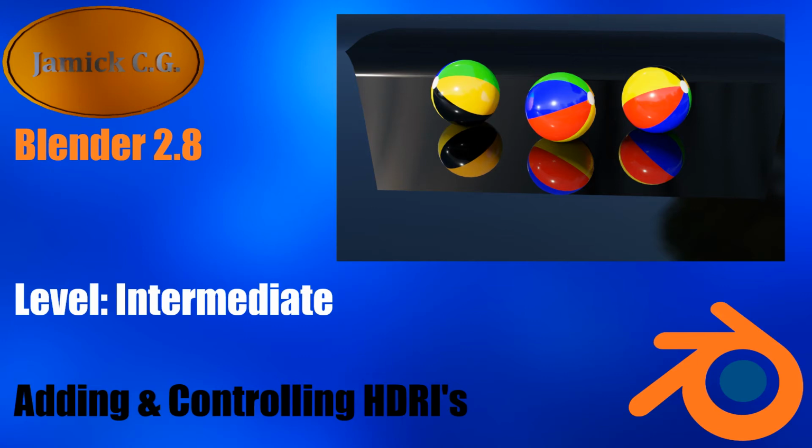In this Blender tutorial, I will demonstrate how to add an HDRI background to Blender, and how to control the position of the HDRI. HDRIs, or high dynamic range images, give scenes better lighting and reflections than other lighting sources.